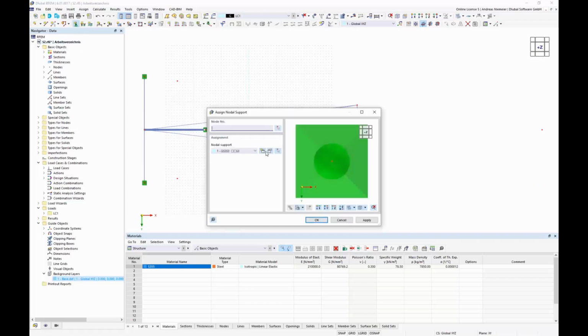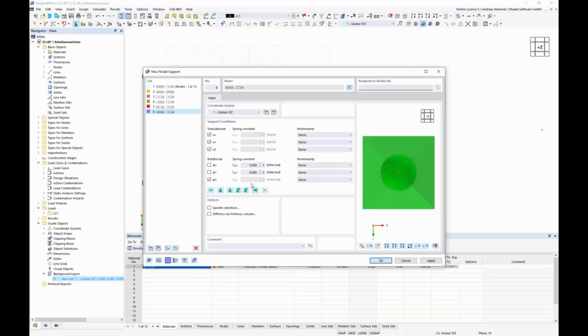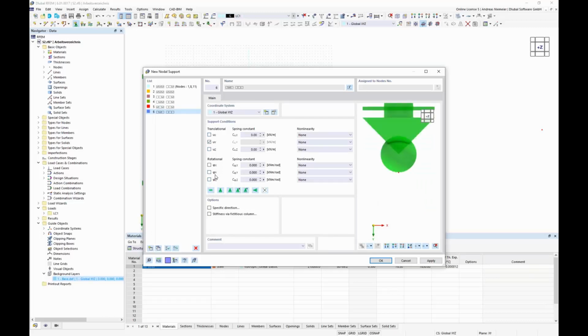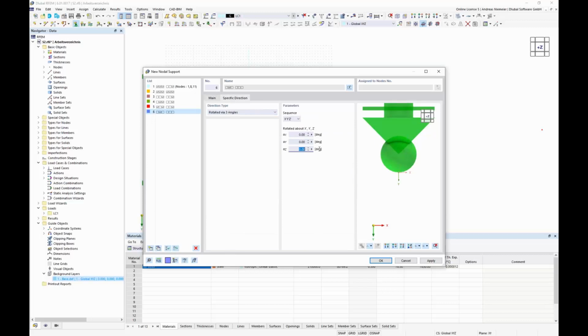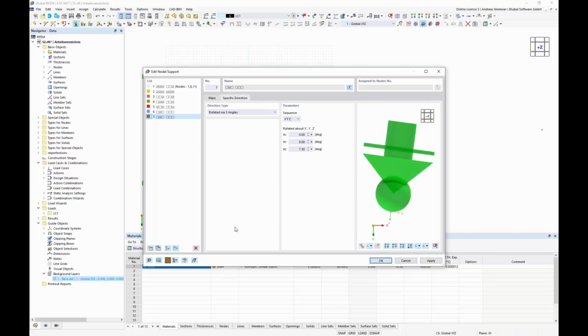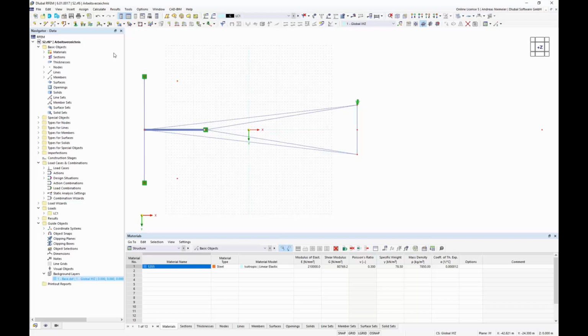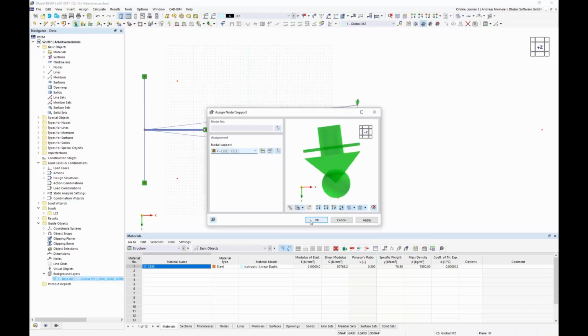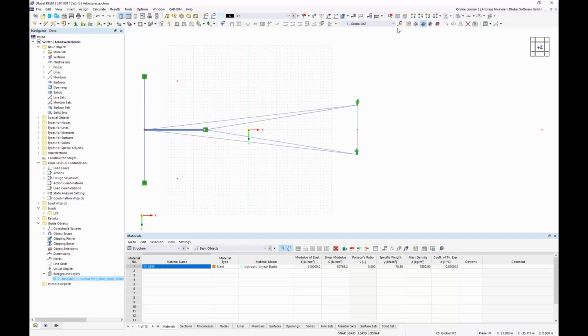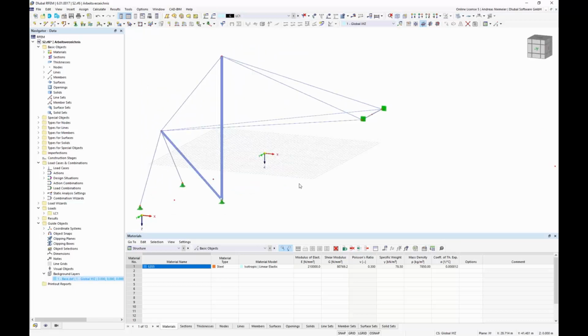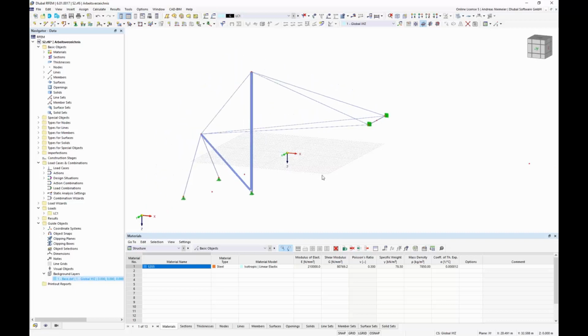For this I use also nodal supports, but I rotate it in running direction of the cable, what means I fixate the degree of freedom in UY direction with a specific direction around 7.5 degree. Yes, and now let's copy it that we have it also for the another direction with -7.5. And now we can start applying this support here, and the same, the last for this direction, and we get a structure what can simulate this tension ring. So the structure itself is now ready.